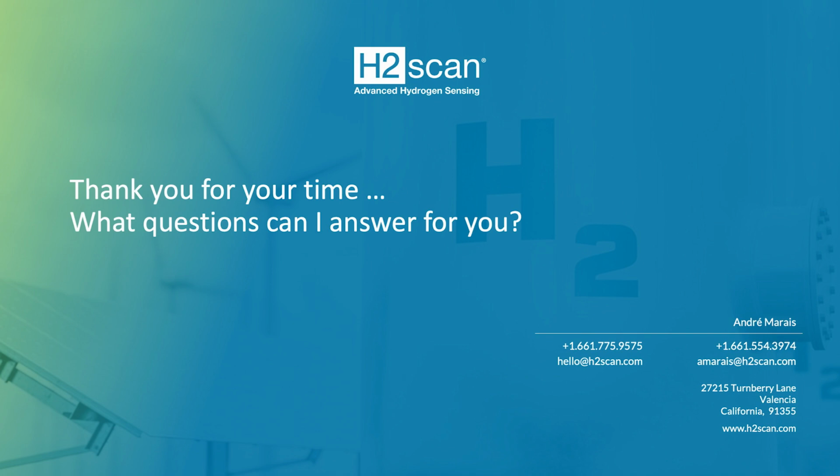And in that duration, other small things would tend to replenish the hydrogen. But in the purest world, if the transformer is really sealed well, zero chance, it would take very long. And so the hydrogen would stay, but in the real world, if it's a very low level, you saw that one example of the case study, it leaked through what I consider a faulty breather or a crack or something, and it disappeared.